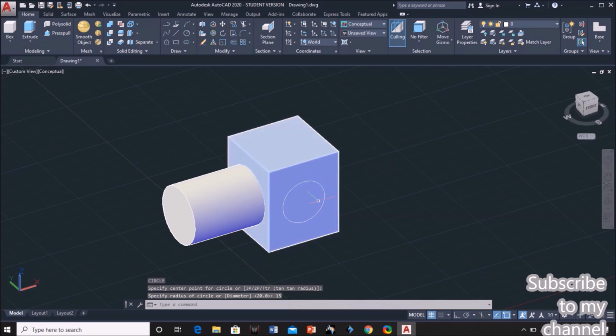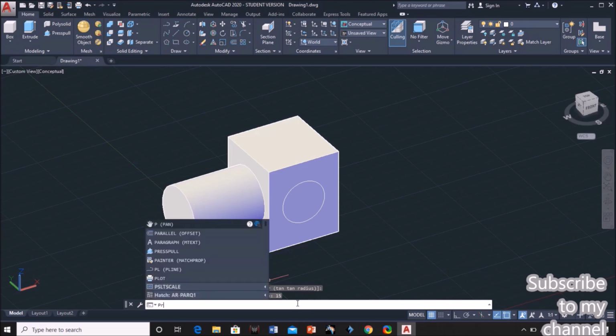Now I need to remove this circle. For that you can use press pull. You need to use press pull for removal or addition of material, whereas extrude is used only for adding material. So use the command press pull.